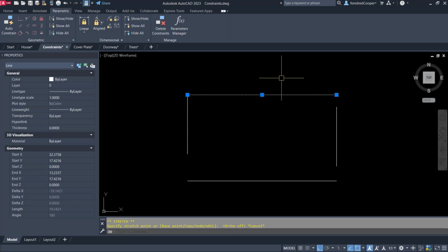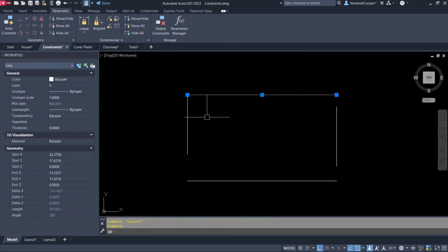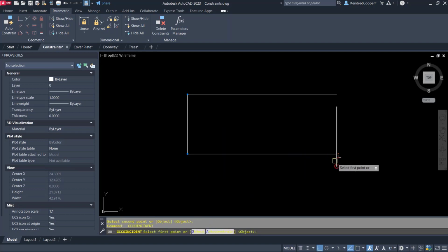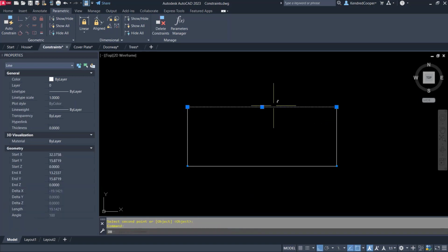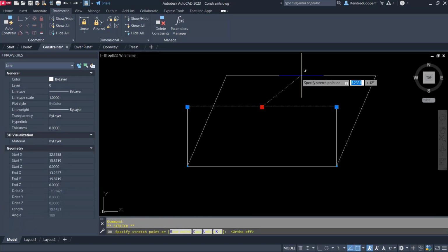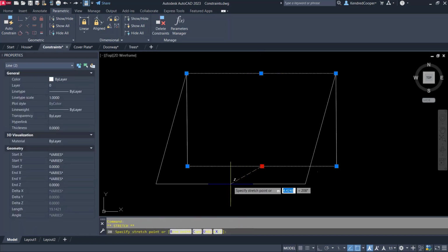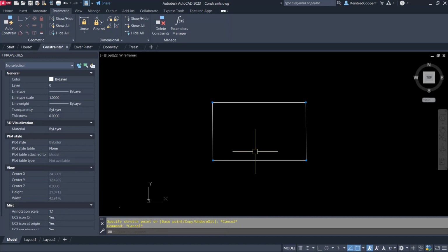So this functions very similarly to what a polyline would do, but it's not a polyline. You're still looking at two individual line segments. I could apply those constraints to the rest of the situation here, constraining these endpoints. And now I can grip it, and that box, all connection points stay connected. Again, similar to what you would see on a rectangle shape, which is a polyline.